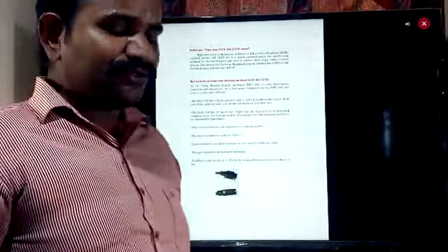So when we are taking the RS232 cable, that RS232 is converting the binary 0 information into the +3 volts to +25 volts range, and the binary 1 information into the -3 volts to -25 volts range. -3 volts to -25 volts range for the binary 1, +3 volts to +25 volts range for the binary 0 in the RS232 case. Just like that, here also, when we are using the IEEE 488